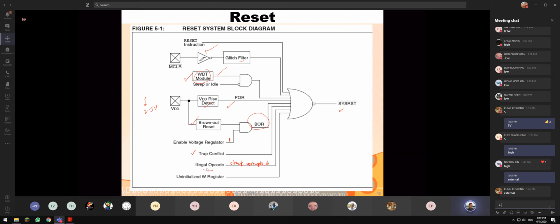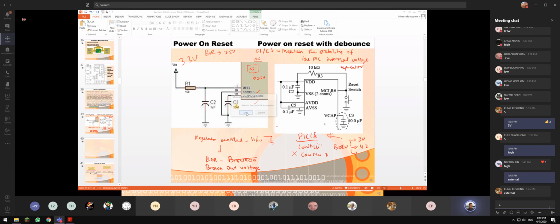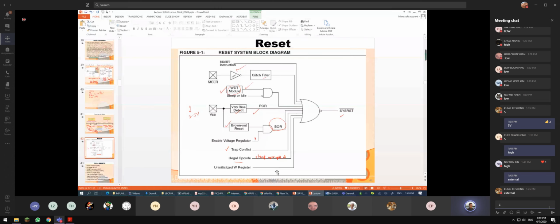Whenever something is wrong, let's say for example the first version of a development board is released, then you switch on power, you test it. Why does it keep on restarting? It's just like a computer sometimes keeps on restarting. Restart has so many reasons. Probably it's overheated, all these things. But the interesting thing about PIC24 is it has a feature. It has a special function register to identify what is causing the system to be reset.